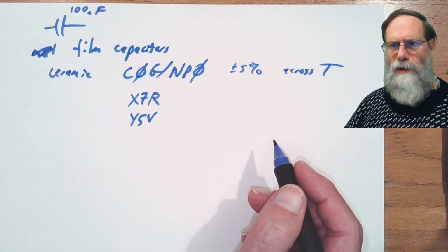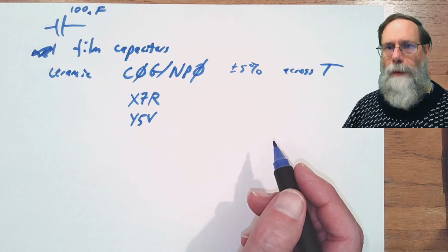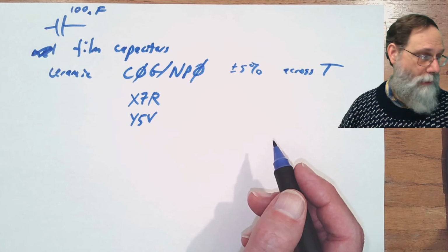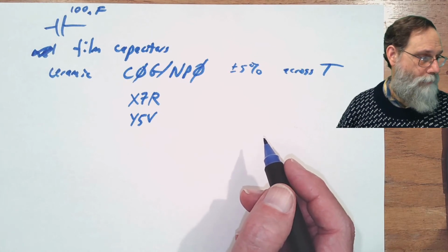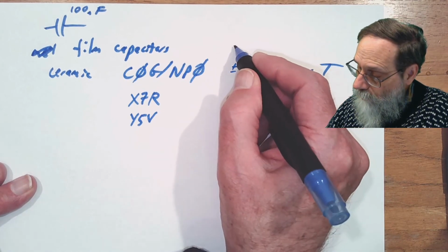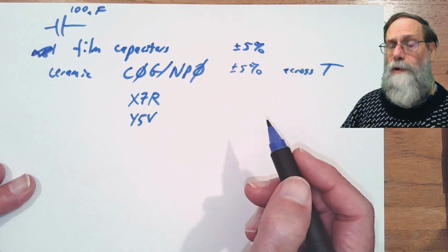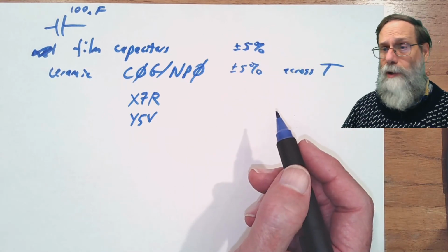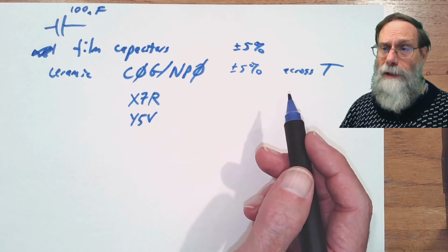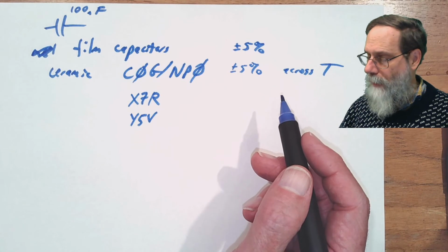So unlike the resistors, there's not usually a big thermal coefficient on the capacitors. There may be some, and the better manufacturers may tell you a little bit about it. The film capacitors, they also are using a fairly low dielectric constant. They're usually using some sort of plastic, so the dielectric constant is only around 2 or so. And so again, you can't get very big values unless you get really large, physically large capacitors.